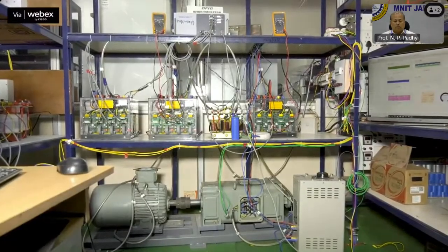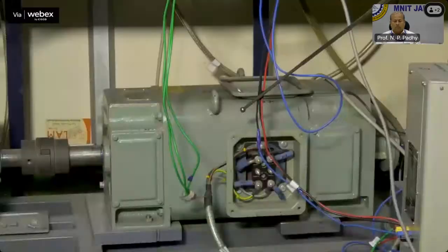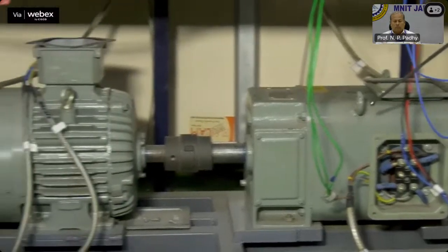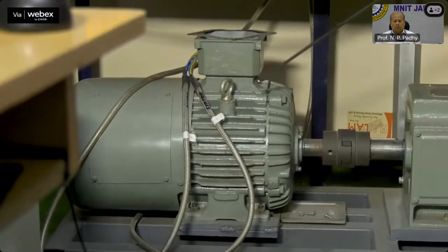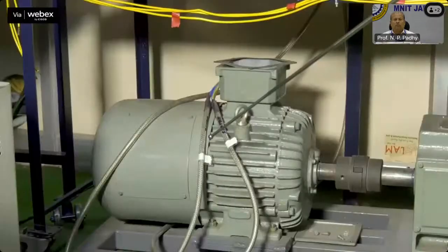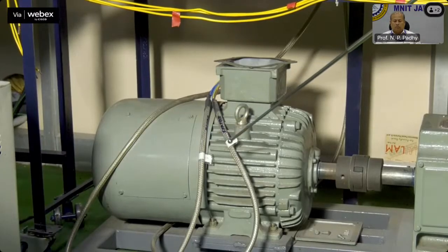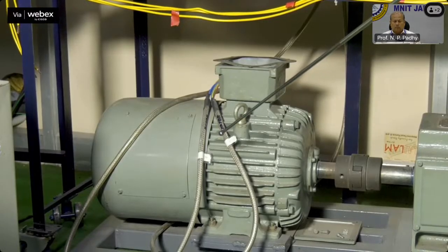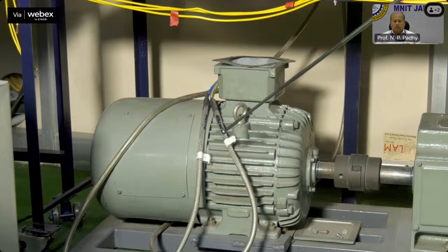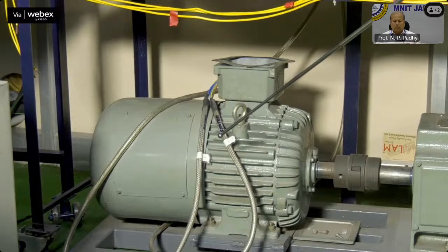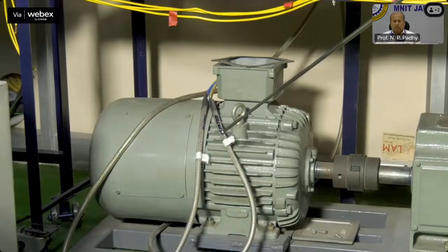The laboratory setup of DFIG is basically a slip ring induction machine coupled with DC motor. This DC motor of rating 2.5 kilowatt, 220 volt, 10 ampere, behaves similar to prime mover and is controlled by chopper control, providing different wind characteristics. For obtaining the wind emulator, the wind characteristics along with the wind turbine action is mimicked with the help of a buck converter.